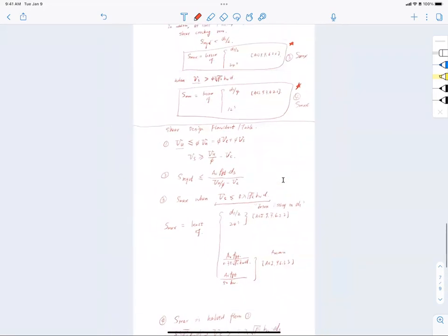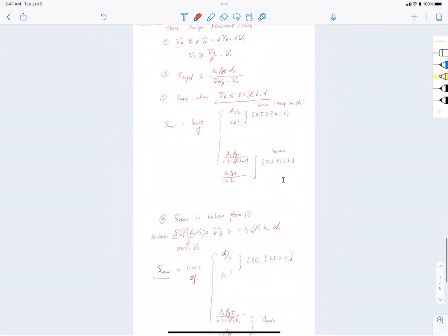Okay, all right, now you see that, right? This is pretty much the process. You start from checking the applied shear against the contribution from the concrete Vc, and then find out the shear resistance for the stirrups Vs. And once you find Vs, you can plug into this equation to find the required spacing. All right. And after you have the required spacing, you need to check if your Vs is smaller than 4 times square root f'c bw d, you do another spacing requirement check to make sure your calculated spacing has to be smaller than maximum spacing.